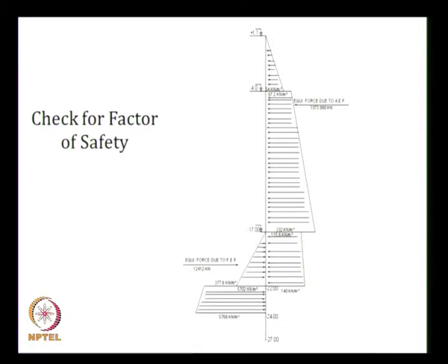This point is clear. Active earth pressure is the force that will be exerted on the structure. Passive earth pressure is the maximum it can be mobilized. Pressure should not be equated, as I have told earlier, only force should be equated. You calculate the force due to active earth pressure as well as the differential water pressure, which is exerted from right to left, while this is from left to right. This should be twice that of this. Up to that you take this founding level.